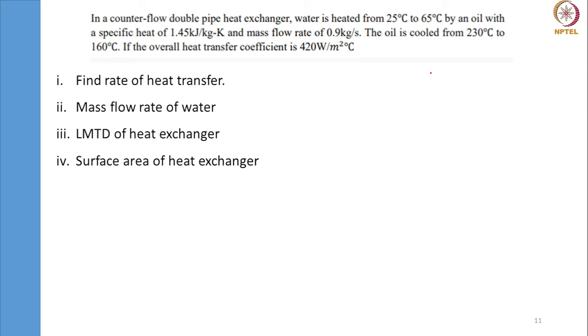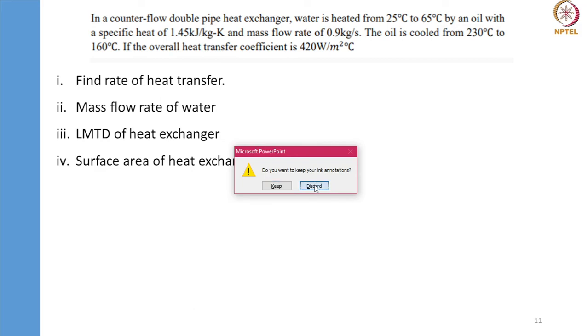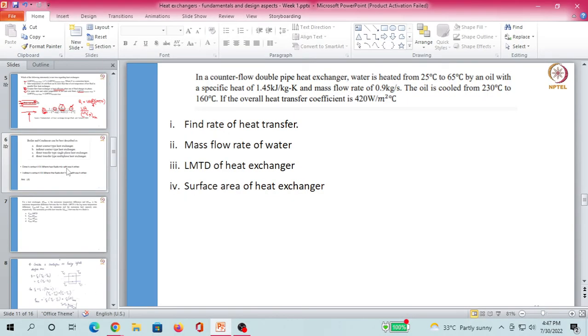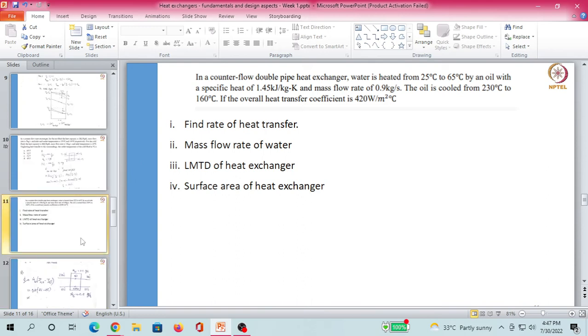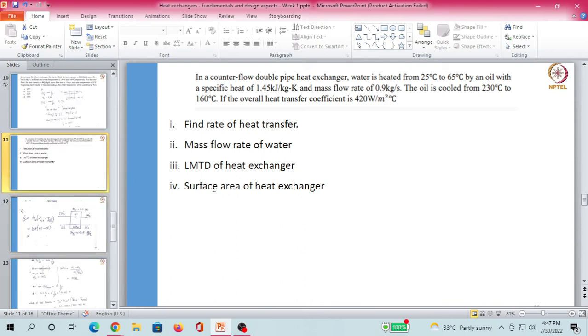Okay, just a minute. I think I made a mistake. These are specific heat and mass flow rate of oil. No? Oh. The mass flow rate of water is not given. Okay. Yeah, so there's a mistake. So it would be 91.35 kilowatt. Okay. I have now calculated in terms of oil. So one of your friends says the heat transfer rate is around 91.3 kilowatt. Any other answers?